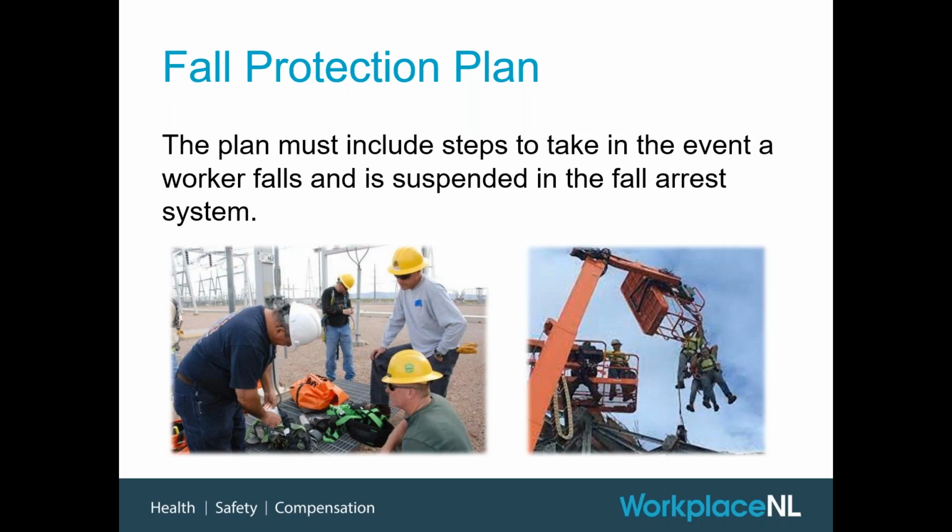need to be timely. It's very important that that person is not suspended for any longer than they have to. I've seen a lot of different options for rescue plans over the years. I just wanted to kind of highlight one or two. When working out of a lift, I've often seen that the rescue plan is to have a second lift go underneath the individual who's suspended and bring them to the ground. Again, due to the timing and how important time is when someone is suspended, that second lift should be ready to go.